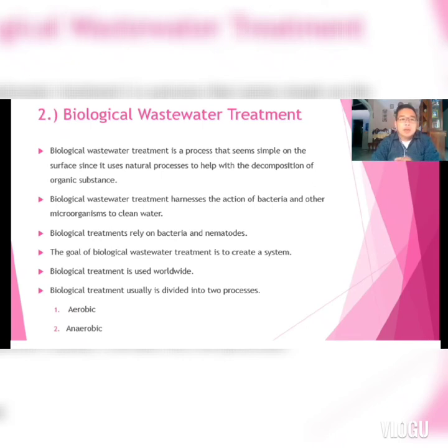Next is the anaerobic. Microbial reactions take place in the absence of molecular free oxygen. Reaction products are carbon dioxide, methane, and excess biomass. It suits wastewater with medium to high organic impurities, or COD greater than 1,000 ppm, and easily biodegradable wastewater. An example is food and beverage.